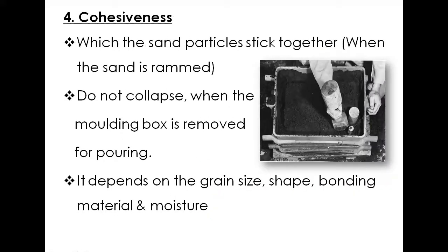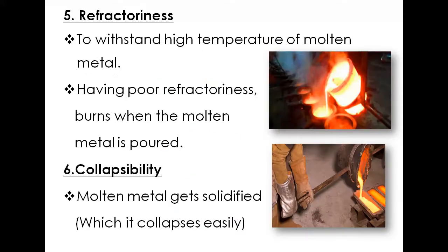Cohesiveness, by which the sand particles stick together when the sand is rammed and do not collapse when the molding box is removed for pouring. It depends on grain size, shape, bonding material and moisture. So here each and every particle sticks together. It helps in bonding them.